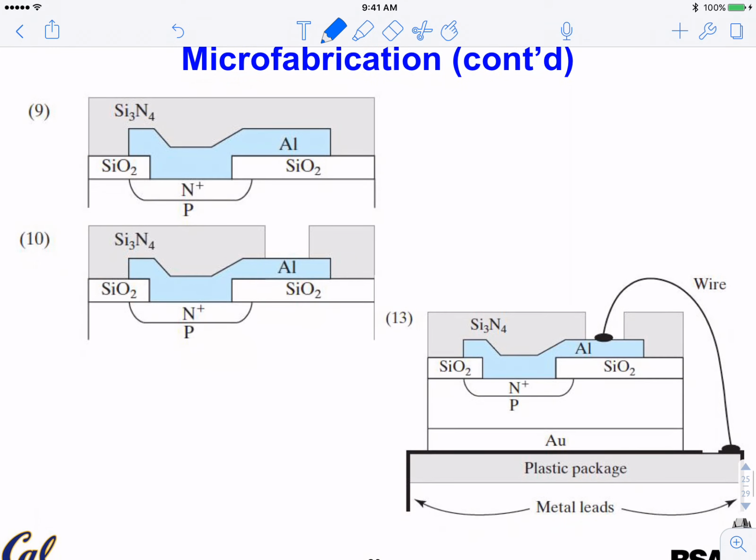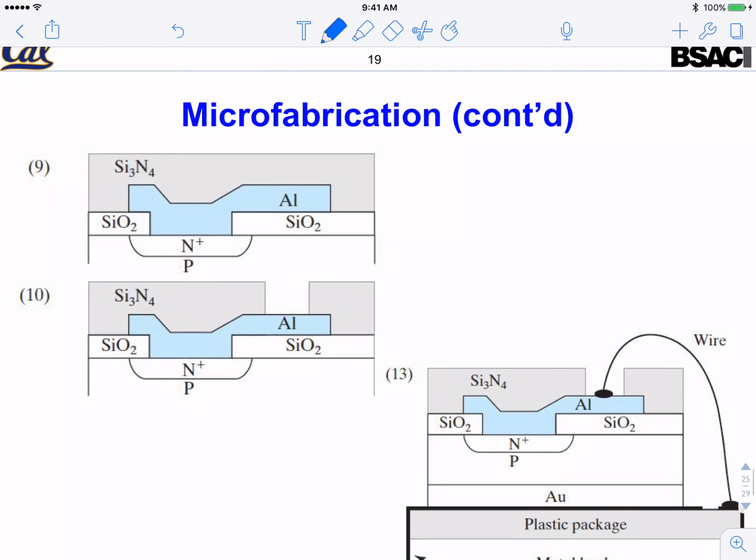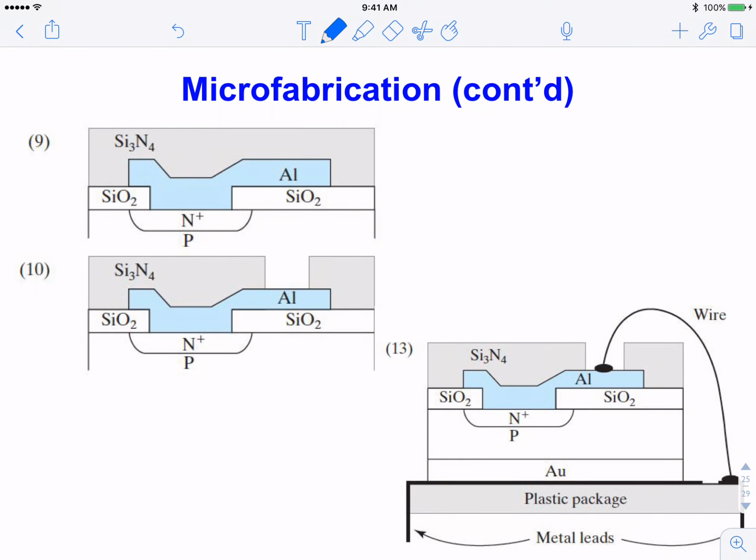And usually when you get your chip, there are some kind of passivating materials. Silicon nitride is used here. In the simplest process, that's it. If you buy a discrete p-n junction diode, then you dice it up. That's the p-n junction diode you get.